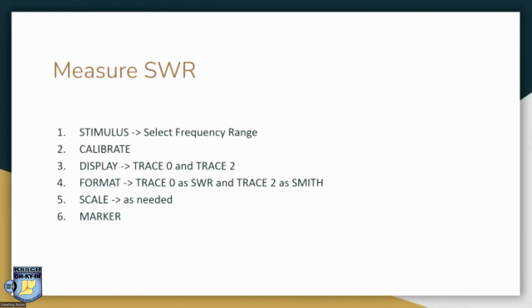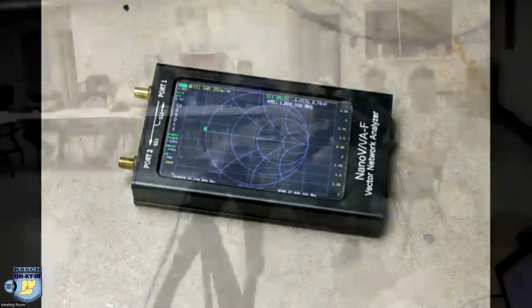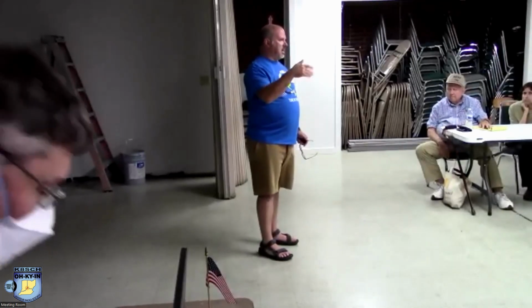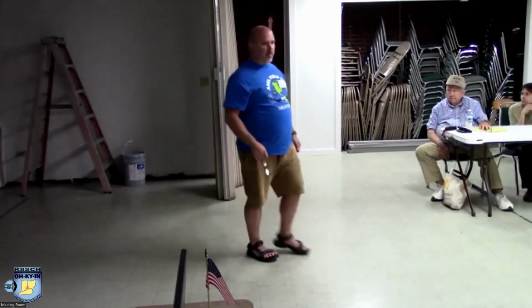Yeah, there are a couple things. I apologize, I forgot a couple of the test pieces. I was going to show measuring capacitance. I had a rough time with capacitance, and part of the reason is, remember, capacitance and inductance are very much dependent on frequency. There was a trick that some guy had that made really good sense: look for your phase angle to be complete reactance. And it worked out pretty well. I'll talk about how to do that in a minute. Okay?